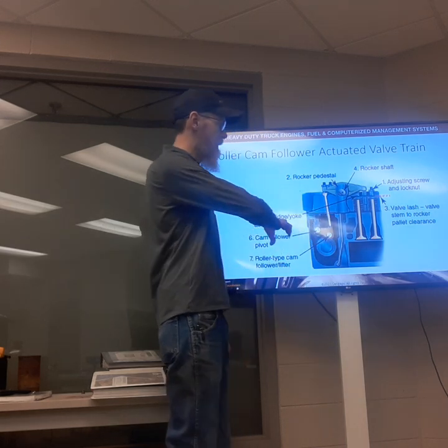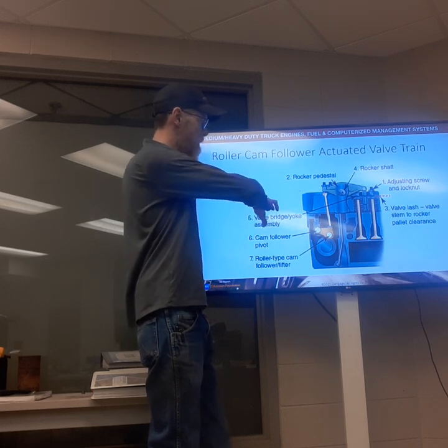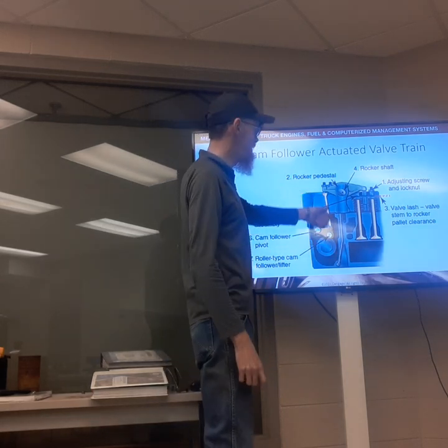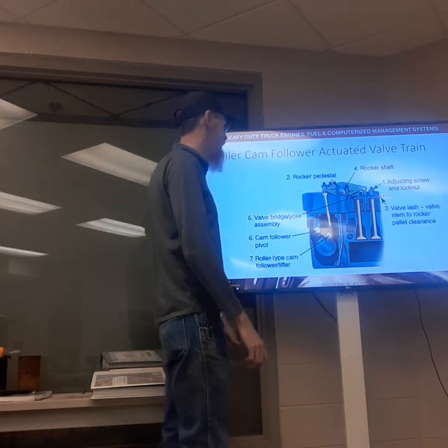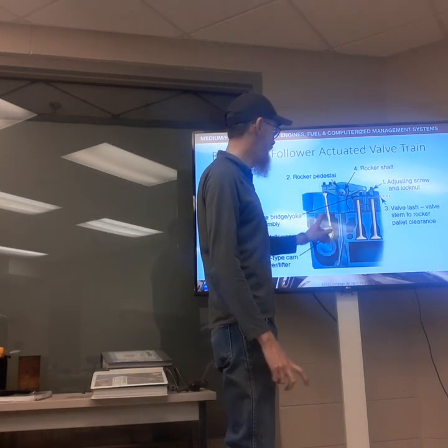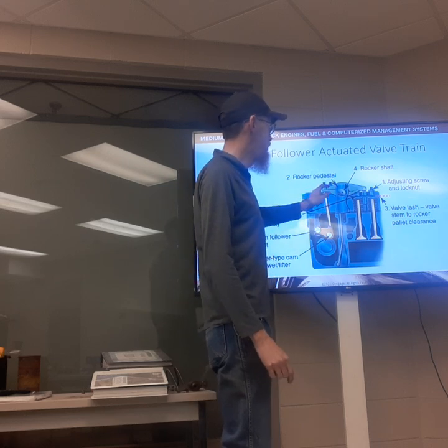And as our cam rotates, that cam follower rides on that cam lobe. And as the nose of that cam lobe rolls around, it pushes up on our push rod, which transmits that linear movement to our rocker arm.